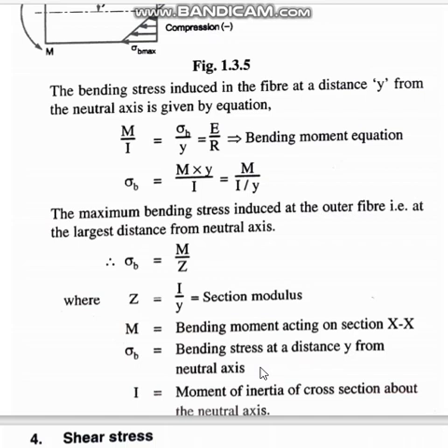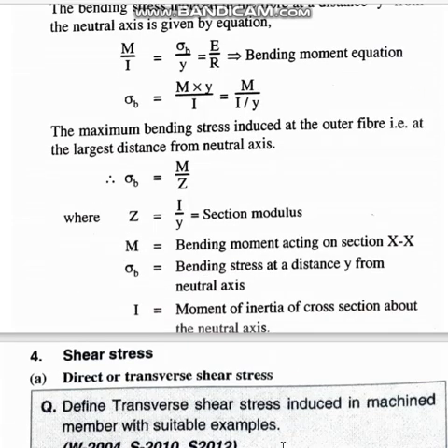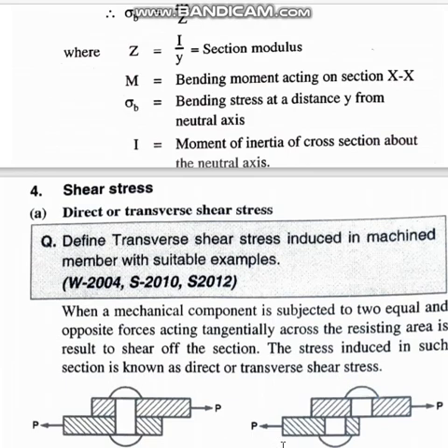If the component fails, or if it gets some cracks or gets damaged, the crack will initiate at the extreme fiber. And I is the moment of inertia. So this is the formula we'll be using. We'll be dealing with bending stress further when we solve some problems.